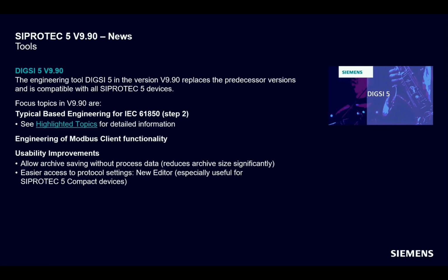What are the focus topics in DIGSI 990? Focus topic is the type-based engineering for IEC 61850 Step 2, which is later on also presented by us under the highlight topics. Another one is the engineering of Modbus client functionality. And we have some usability improvements.